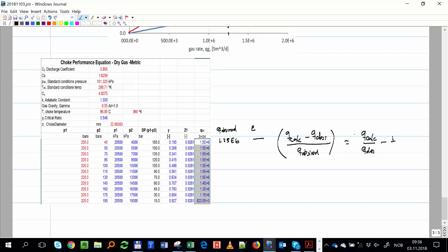So when I take that difference, this is a number between 0.5 and 1.5, for example. So this will always be a small number, and the solver likes to have this small number. If I don't normalize Q calculated minus Q desired, this number might be extremely big, because I'm talking here in millions. So solver doesn't like these really big numbers.